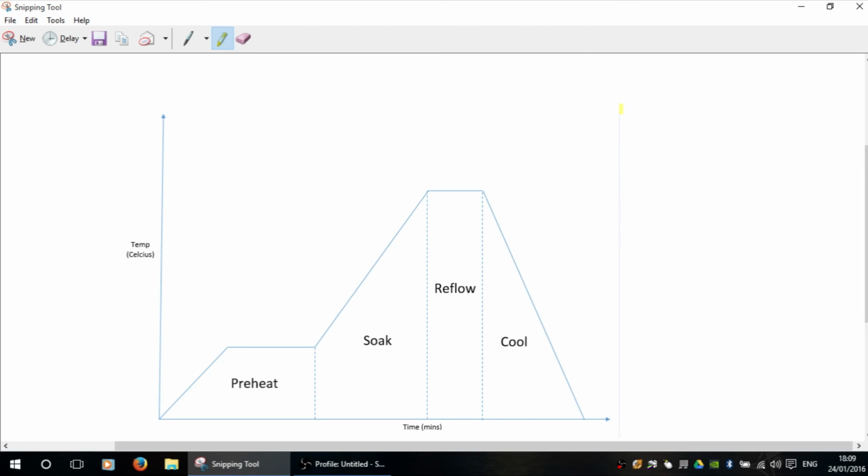That metal does go some way to absorbing some of the heat we put into that chip. And then, of course, you've got things like the RSX and Cell processors from the old PS3s, which have a fully integrated heatsink in there, which draws away a lot of the heat that we put into the BGA. Without proper rework and care and attention in our profile, we're either not going to lift that successfully, we're going to damage the board, or worse, we're going to damage the chip.